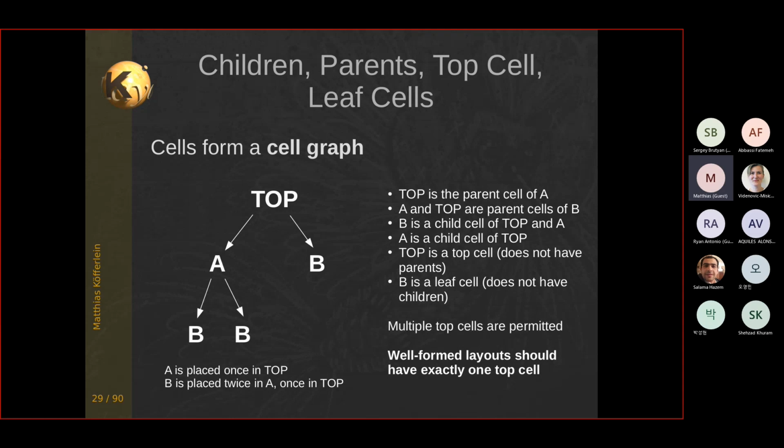And as a hint from my side, if you deliver a layout to some mask maker, make sure it has a single top cell, because it actually happened that they took the wrong one and you have the wrong version of your design on the mask. And if that one happens to be non-functional, then you're in a lot of trouble.